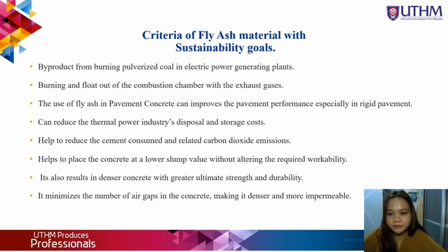So the criteria of fly ash, the material that we use for sustainable pavement design: this material is a byproduct from burning pulverized coal in electric power generating plants. It floats out from the combustion chamber with the exhaust gases. The use of fly ash in pavement concrete can improve pavement performance, especially in rigid pavement. It can reduce the thermal power industry's disposal and storage costs, and it also helps reduce cement consumption and the related carbon dioxide emissions.